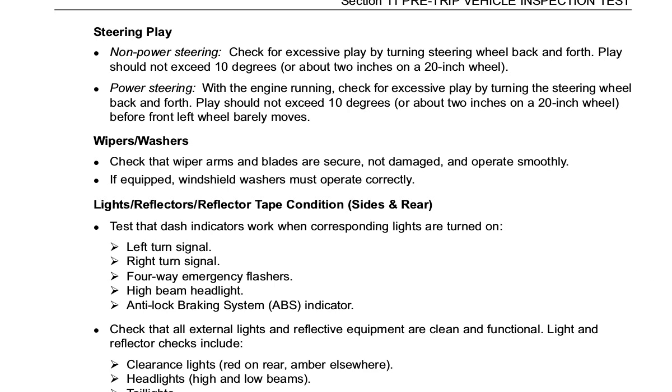Wiper washers. Check that wiper arms and blades are secure, not damaged, and operate smoothly. If equipped, windshield washers must operate correctly.